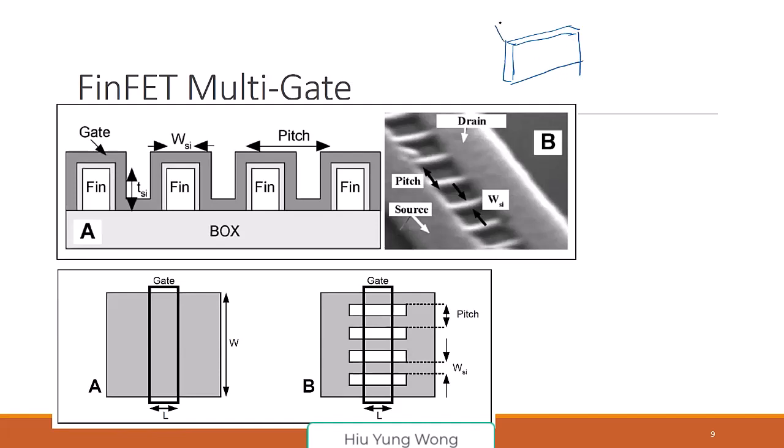And then we say, okay, I have a big structure here. Let me not draw it. I can never draw it well. Source, drain, right? And then we have a gate. This is a FinFET. Is that okay, everyone, about what I'm drawing, a FinFET? But in reality, we actually won't rely on one fin. So this is S, this is D, and this is the fin without the gate. Okay, this is the fin. And we have many fins.